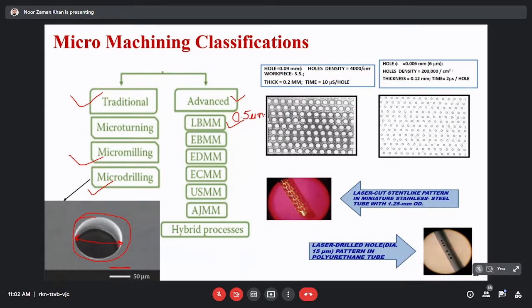So it is used in producing MEMS, micro electromechanical systems. Laser beam micromachining is highly used in micro electromechanical systems. If we take examples of these systems, like computer hard disk drive heads, inkjet printer heads, sensors, or IR imagers. And if we talk about modern printers, they have a nozzle of size around 300 by 28 micrometer.